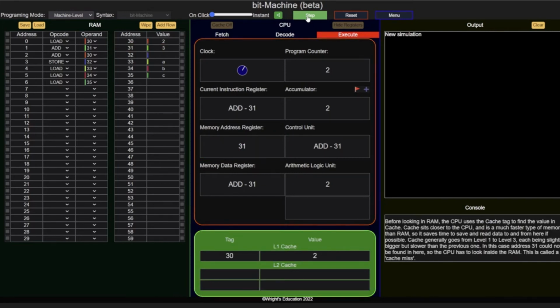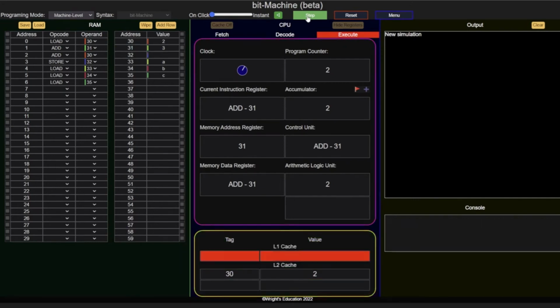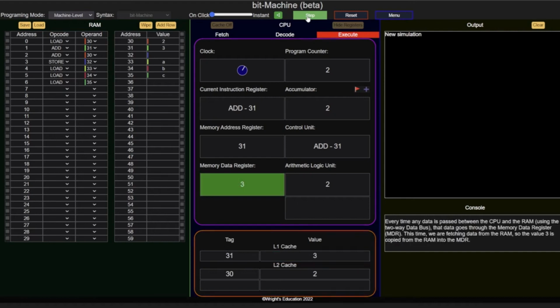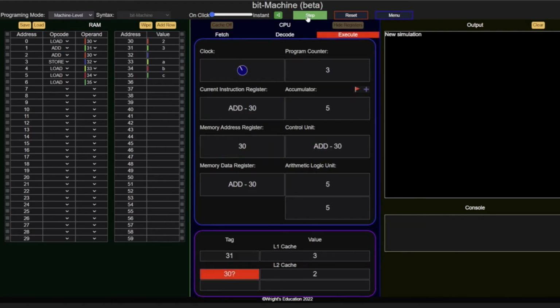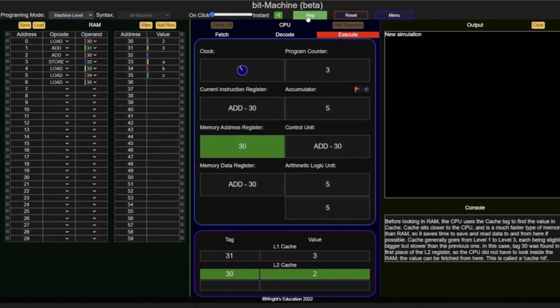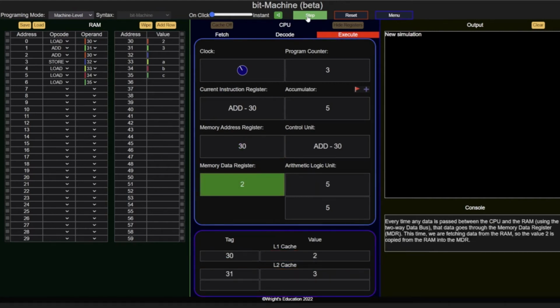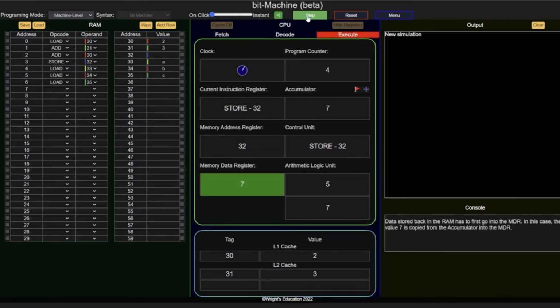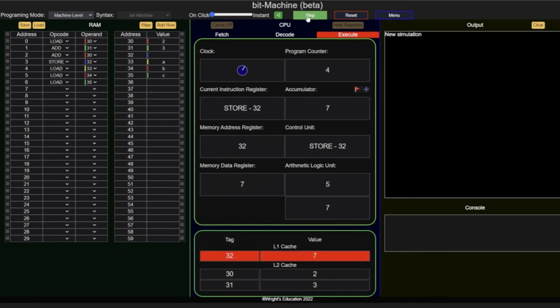ADD stands for add and it will take the value of the specified memory address and move it to the buffer register, known as reg B or register B. During program execution, the content of reg B will be summed with the contents of reg A and it will be indicated in the sum register. The value from the sum will then be moved to reg A where it can be used later in the program. The instruction accepts a single hexadecimal input which corresponds to the memory address of the value to use.